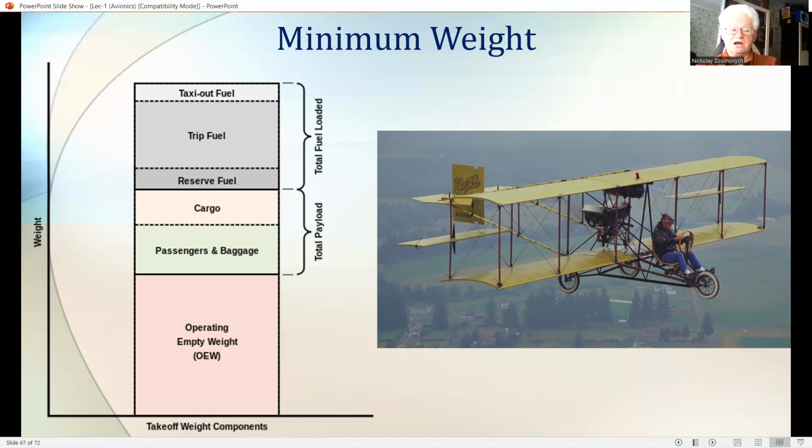An increase in the aircraft weight due to, say, an increase in the weight of the avionic equipment requires the aircraft structure to be increased in strength and therefore made heavier in order to withstand the increased loads during maneuver, assuming the same maximum normal acceleration is achieved and the same safety margins on maximum stress level are maintained. This increase in aircraft weight means that more lift is required from the wing, and the accompanying drag is thus increased.